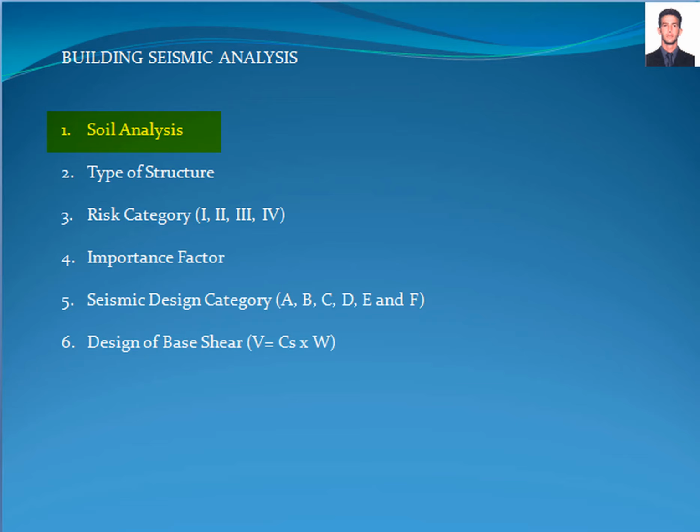long period transition period, from which we are going to calculate the site coefficients FA and FV for the short and long period, the expected response acceleration SMS and SM1 for short and long period, and the design expected acceleration parameters for short and long period, SDS and SD1.